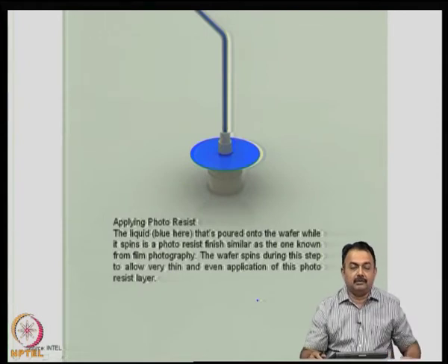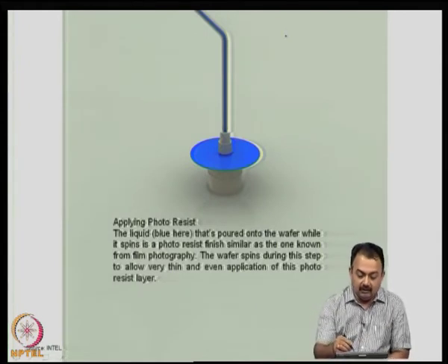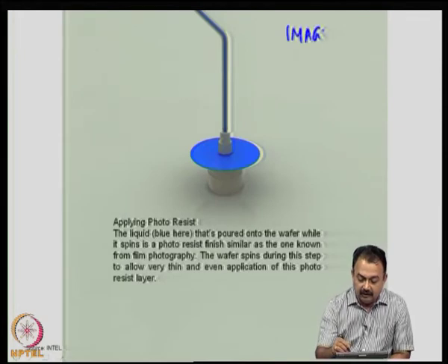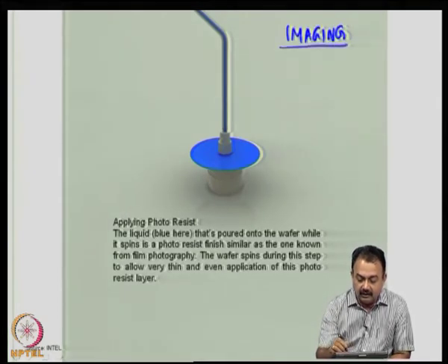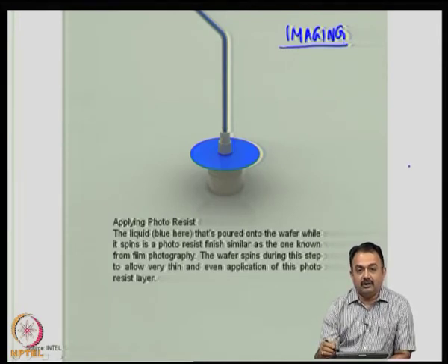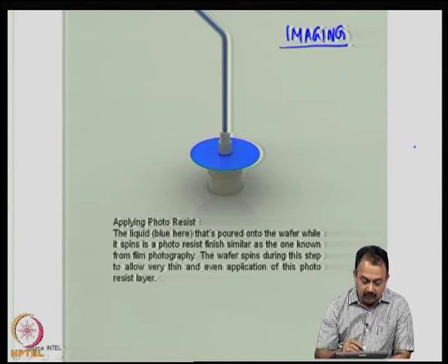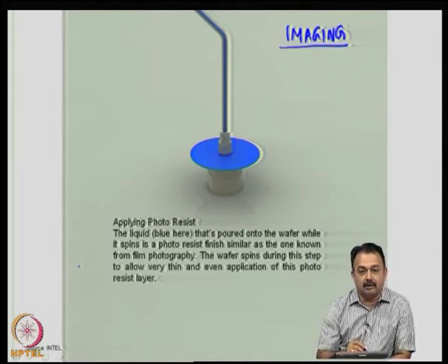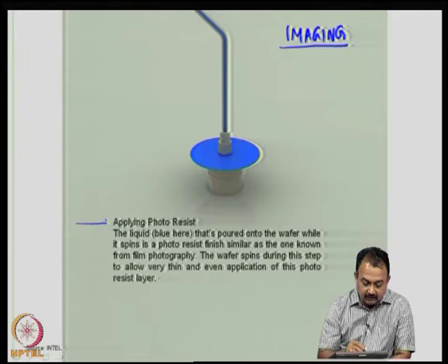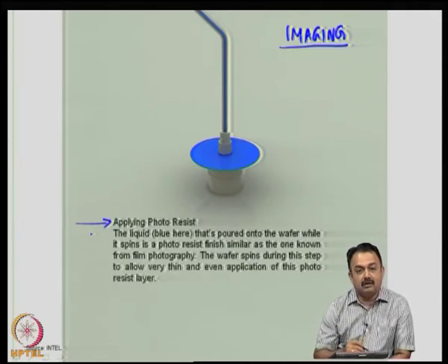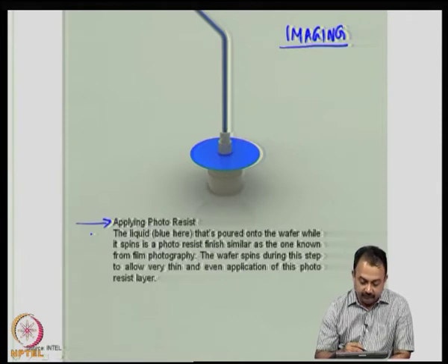Now, the next step is typically imaging, but for imaging your CAD design onto the surface of the wafer, you need a medium that will take up your design and realize it on the wafer. So, we go through what is known as a photoresist application process. Therefore, the next step is applying photoresist on the surface of the silicon wafer. In this picture, the blue color depicted is the liquid photoresist material that is applied.